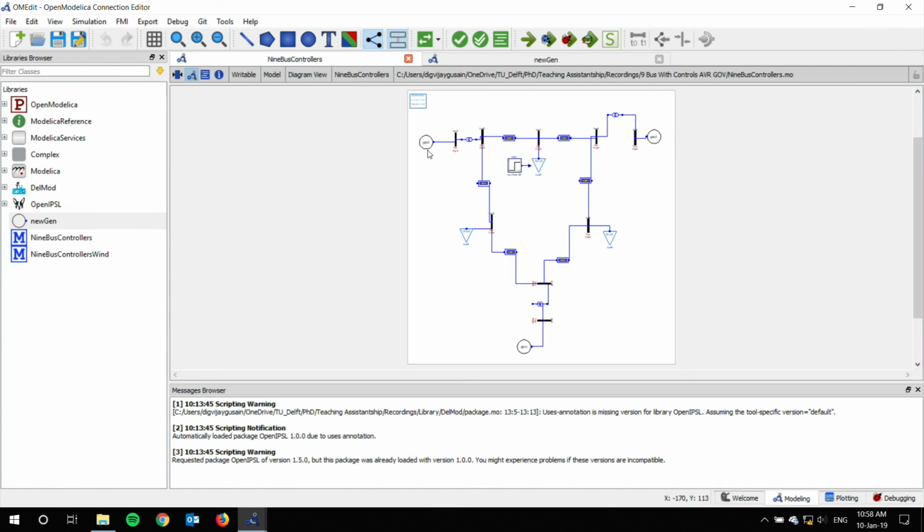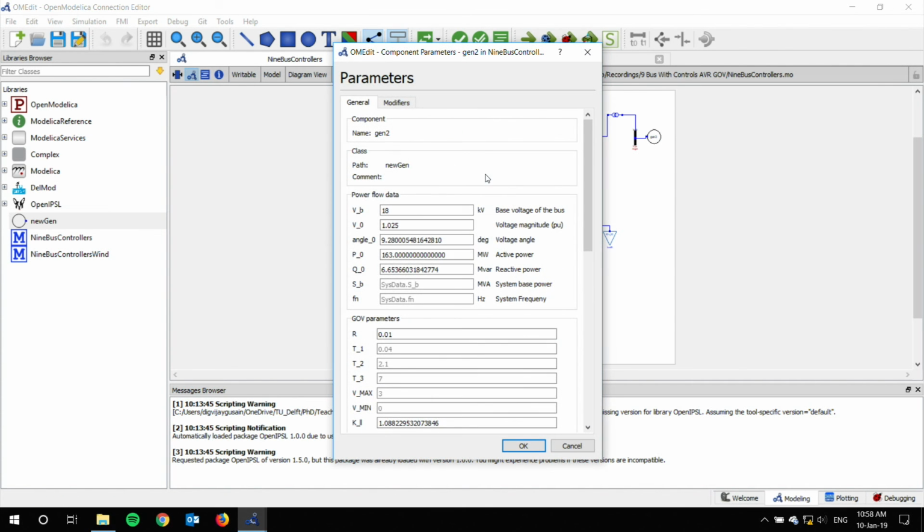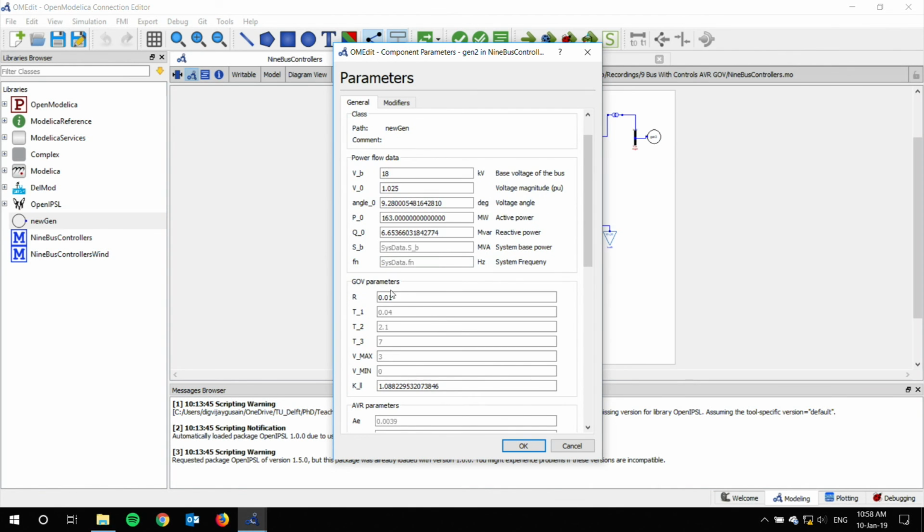Open any generator dialog box, it should now contain options to set governor parameters. The generator properties box opened from Network Model Workspace is also given in figure 5 of the modeling companion. These values can now be populated for each governor. The values for each generator governor are given in the tables section 2 of the modeling companion.